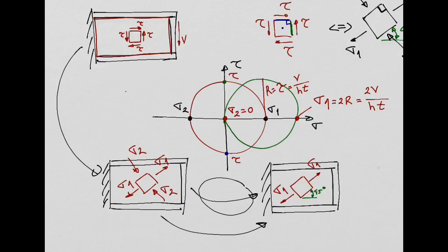Because we then calculate the forces in the flanges, in the posts, the stresses in the web, and we make sure that all these different structural components are able to carry the overload they are getting. So we could do more examples, but this is it. Only the dimensions and geometry will change, the loads might change, but this is all about it.